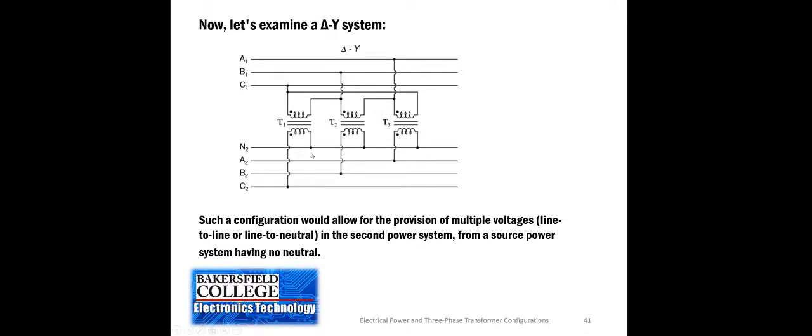So in this case, by using a Y configuration, all three transformers feed the same neutral. So if we balance the single phase loads, the lower voltage loads between neutral and A, neutral and B, and neutral and C, then the current would be pretty even on the three transformer coils. So that's an important reason why the output is most commonly Y rather than delta.